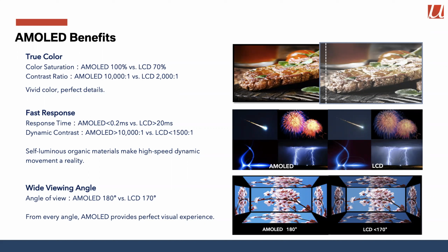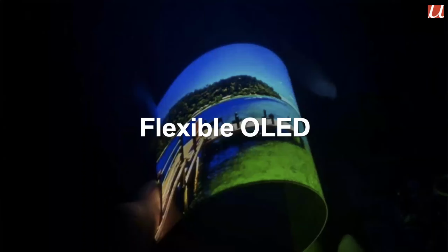And finally, modern LCDs are pretty good for the viewing angle, but the AMOLEDs are really, really good because the light is being emitted directly very close to the surface of the display itself. So pretty nice technology, and where we're headed now is let's go and make those flexible. And it turns out that that's not particularly easy to do, but it can be done.